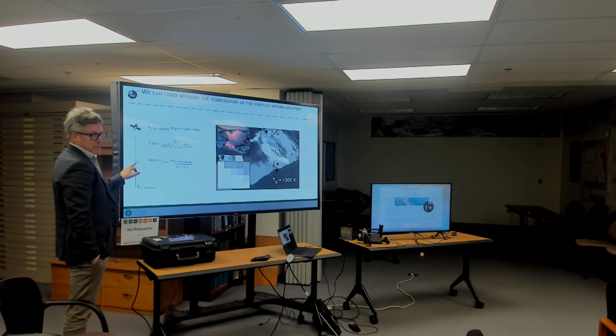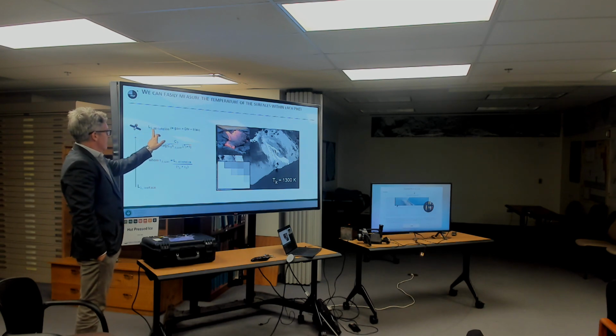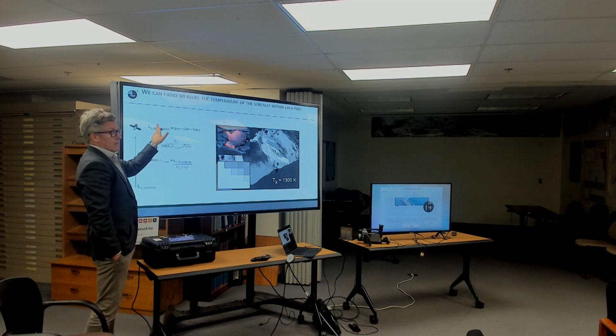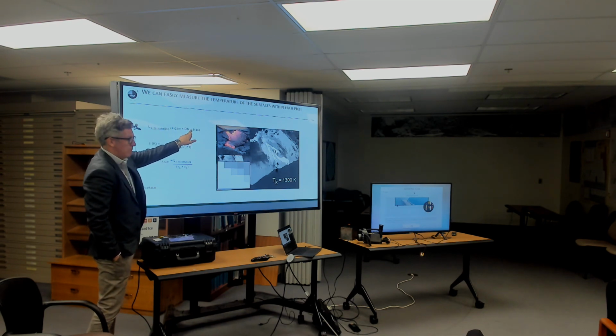That energy passes up through the Earth's atmosphere, which has a transmissivity which is less than 1, so we have to account for it. And at the satellite here, what we end up with is a thing called at-satellite spectral radiance. And I showed you that we typically have these calibration relationships where L lambda equals gain times a DN plus a bias, equation of a straight line type thing.